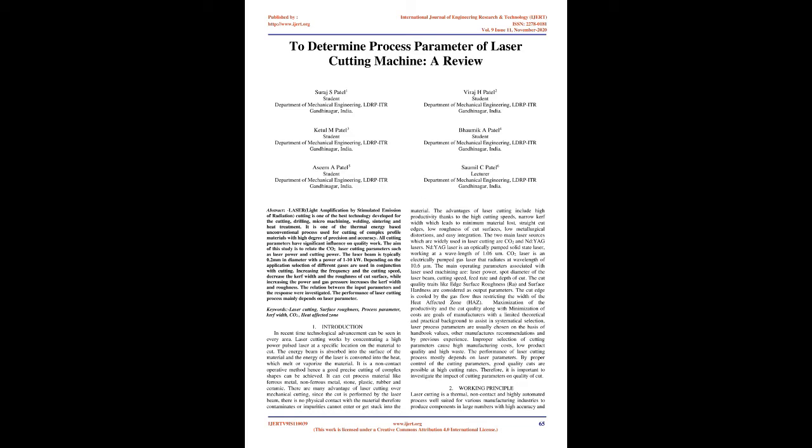Saumil Patel, Lecturer, Department of Mechanical Engineering, LDR-PITR, Gandhinagar, India. The advantages of laser cutting include high productivity thanks to the high cutting speeds, narrow kerf width which leads to minimum material lost, straight cut edges, low roughness of cut surfaces, low metallurgical distortions, and easy integration.